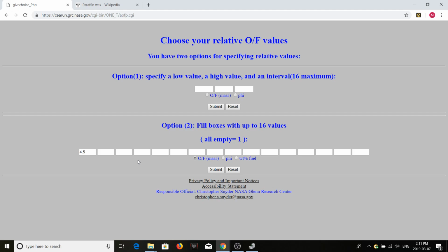You'd have to strip the data from the output file using a script, but you could effectively generate a 2x2 array of the combustion chamber gas properties based on varying chamber pressures and oxidizer fuel ratios to analyze a given fuel combination over different scenarios. Then you can repeat this process for a different fuel combination. We don't need to do that here though.